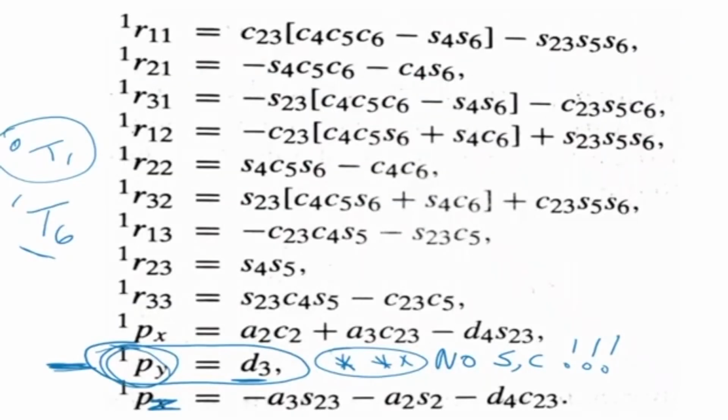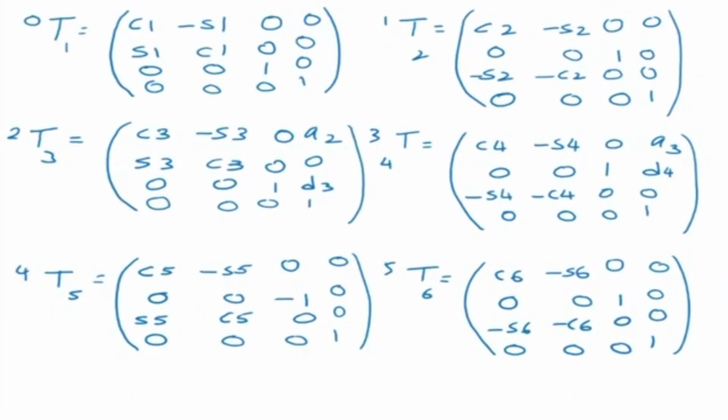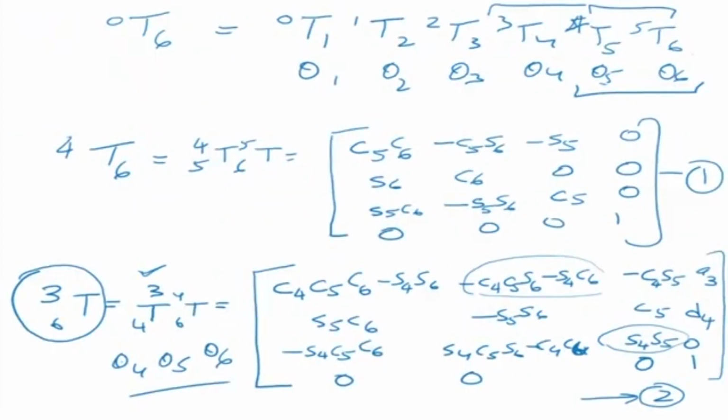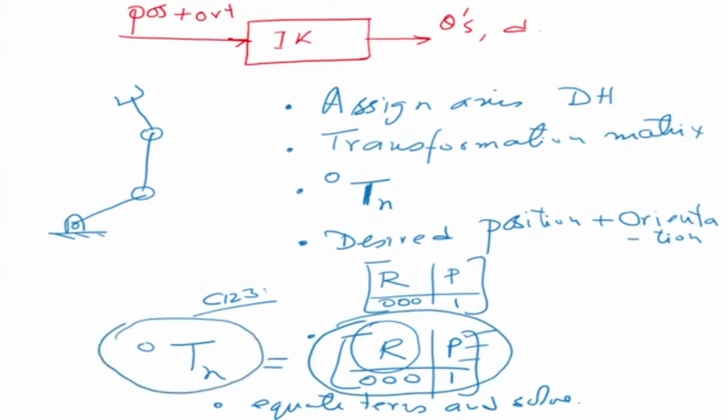So let's look a little bit into why we were able to solve for this manipulator system, and try to understand what basic logic was used. Let me go back here. When we are trying to solve, this is my desired position and orientation of the end effector, T 0 to n. So the right hand side is known, everything here is known. This part is unknown, and it has variables theta 1 to theta n.